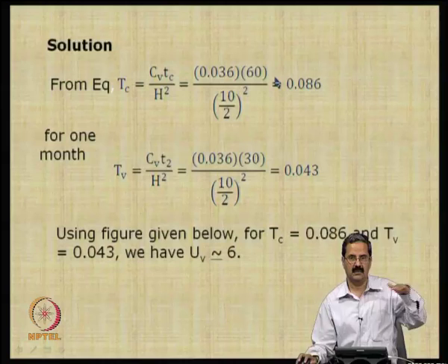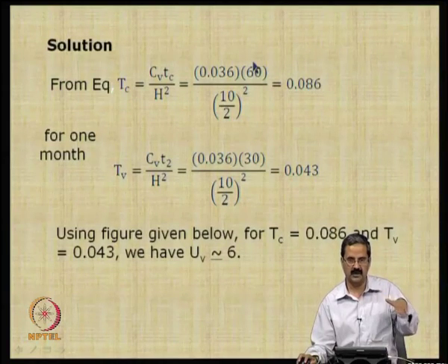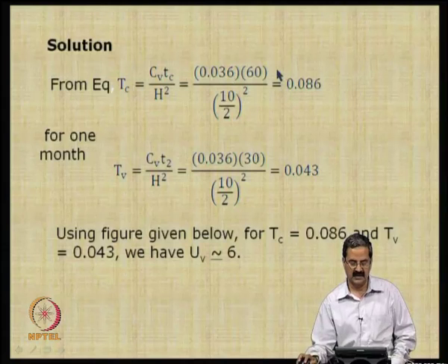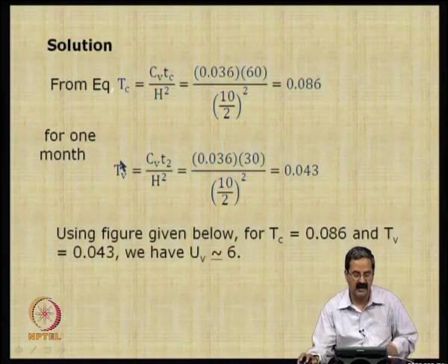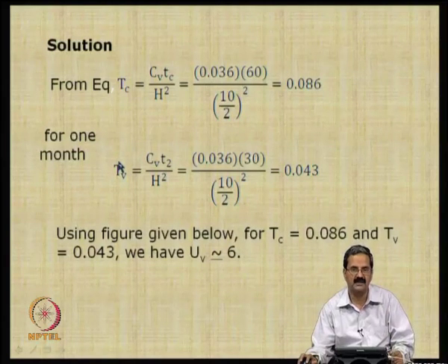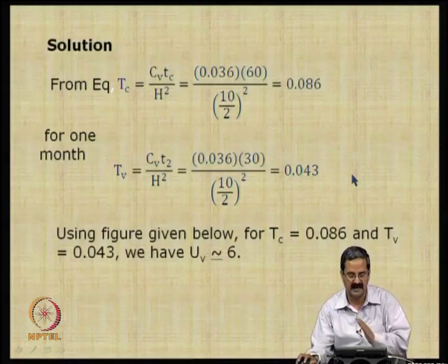this factor corresponds to full load, the top of the ramp load, once you complete that loading, which is about 60 days as I just mentioned. It is fine for 60 days, but you must be able to calculate every month. Our objective is the degree of consolidation at 1 month, 2 months, 3 months, 6 months, like that.